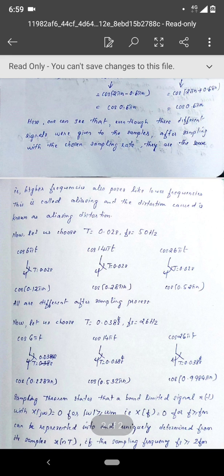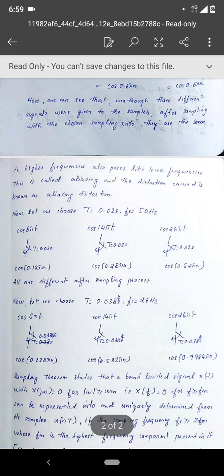So one conclusion is there. Here the output of the sampler circuit is distinct because the arguments inside the cos function are less than pi n. Another takeaway from this example is that the argument of the cos function should be less than pi n. If it is less than pi n, or even equal to pi n, all the components of the signal after the sampling process will remain distinct. Here you can see that 0.12 pi n is less than pi n.